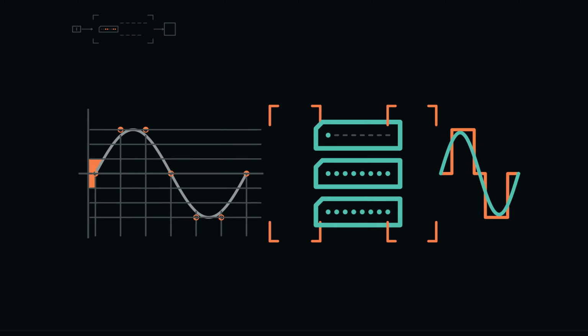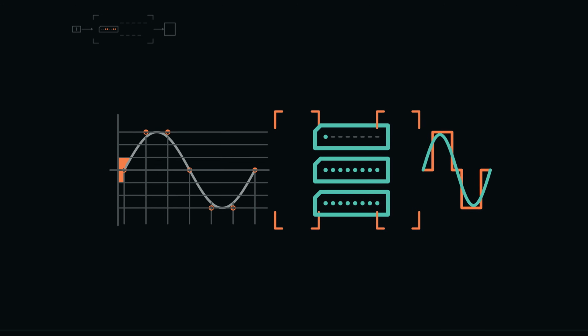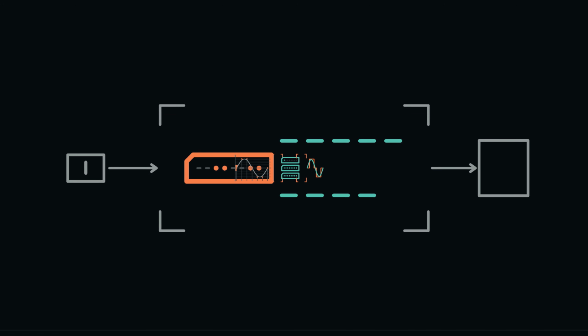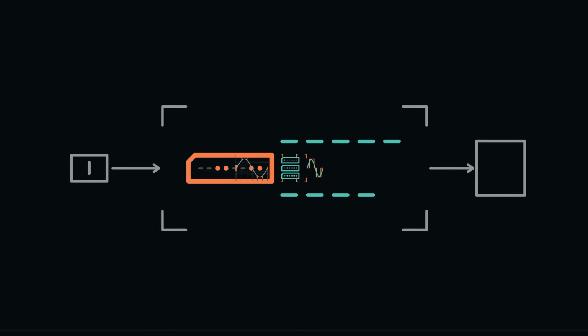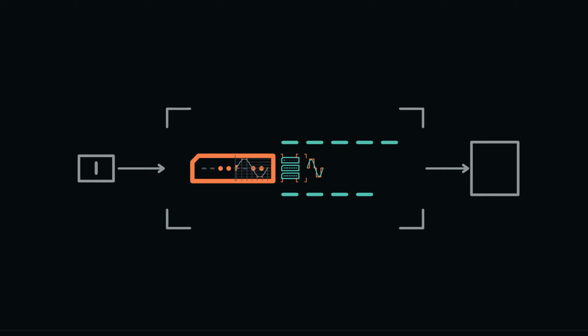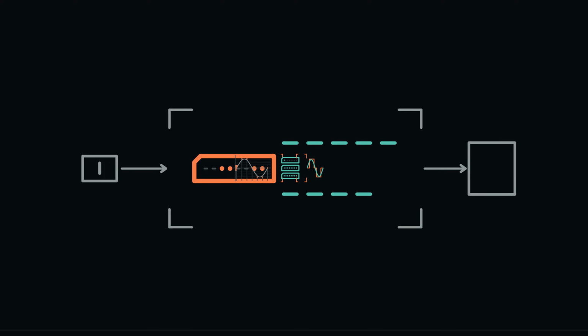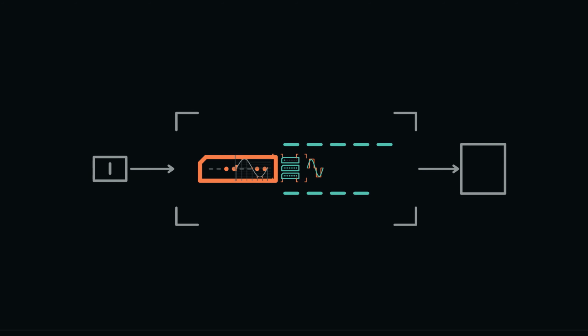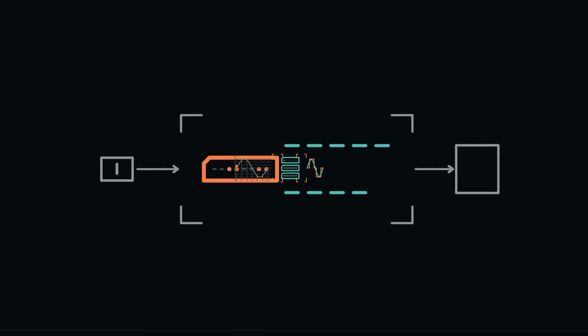Given a new graph, point first to the sample times, then to the available amplitude levels. Ask which changes could occur unseen between samples, which measured values share one quantized code, and which physical limits define the valid input range. On the output side, identify the converter levels and the reconstruction filter. The digital machine now has an honest boundary with an analog world. We can finally compare our clear teaching machine with modern systems, provided every new mechanism states which old contract it preserves.